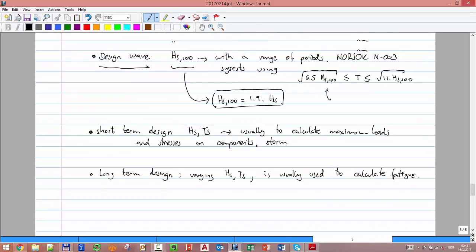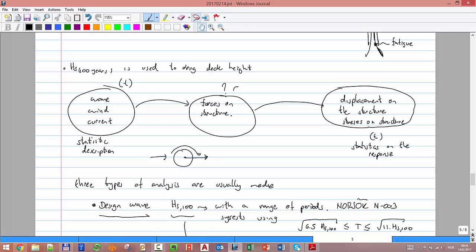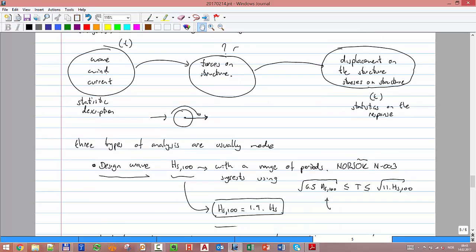If you detect that a certain structure has a certain natural frequency, you want to avoid using it where it would be excited at that frequency. That's something given by nature. You measure in one area that the loads have certain characteristics, so you cannot put in that area a structure that has a natural frequency equal to the excitation frequency, because then it might be destroyed very quickly. So let's put a plot.